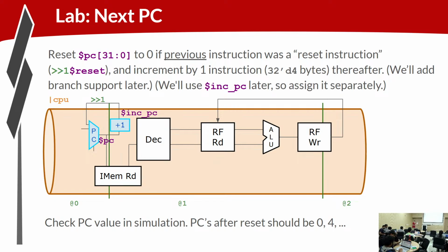The observation is that generally when you structure logic like the PC, the PC mux, which has multiple cases, when you're coding in Verilog, you generally use sequential constructs for something like that, where you would assign a PC by default to be +1, and then you'd have an if condition. If this is a branch instruction, then let's assign it to something different.